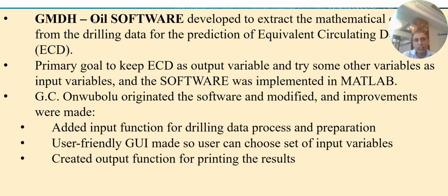So we didn't develop the software, but we updated one of the existing software packages, developed for some other purposes, with our own information. GMDH software was developed to extract a mathematical model from the drilling data for the prediction of downhole equivalent circulating mud density, which comes from the annular pressure of the wellbore. The primary goal is to keep the ECD as the output variable and try some other variables as input variables.